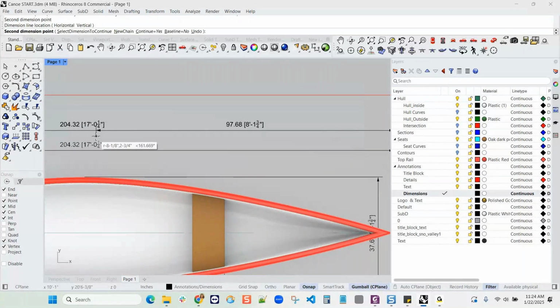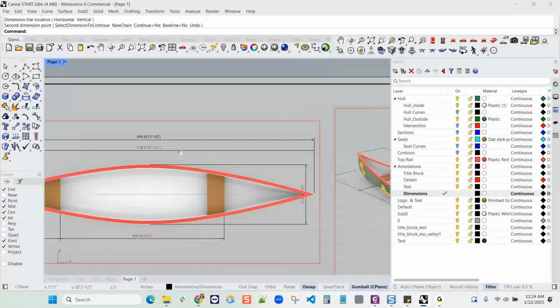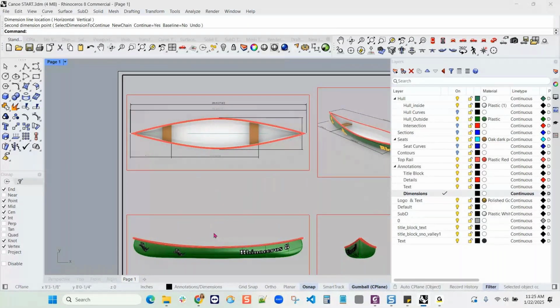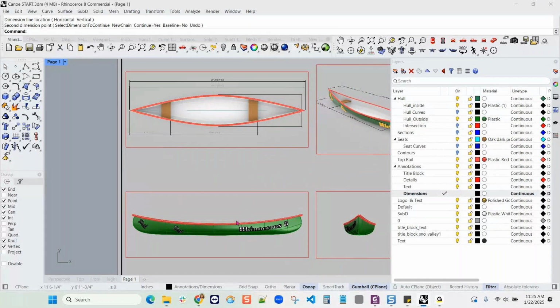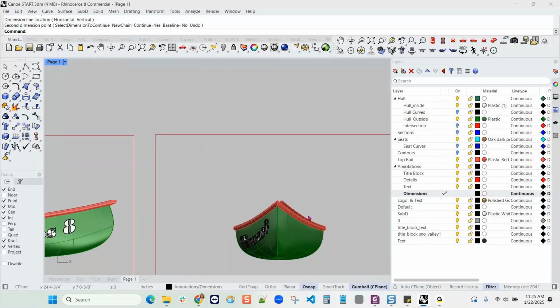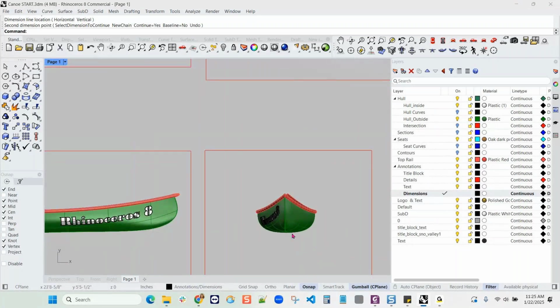So that is an option. It not only looks the same, but because we're using OSnaps, it scales. A lot of times people ask, well, where should I create my dimensions? The answer is you can create them either place, but if you don't want them visible in the model, you can create them on the layout. If you want them visible on other layouts and other details, then you do want to create them in the model.